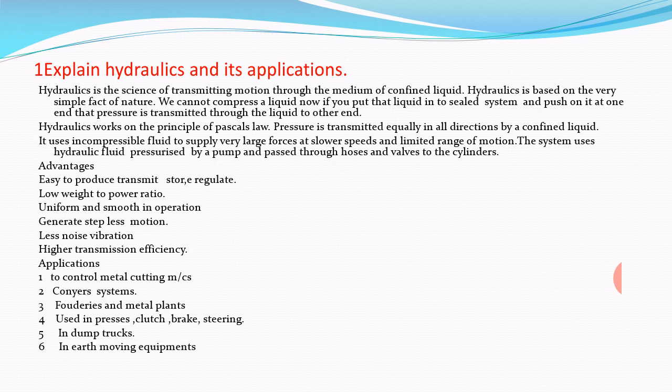If you put that liquid into a sealed system and push on it at one end, that pressure is transmitted through the liquid to the other end. So hydraulics works on the principle of Pascal's law: pressure is transmitted equally in all directions by a confined liquid.